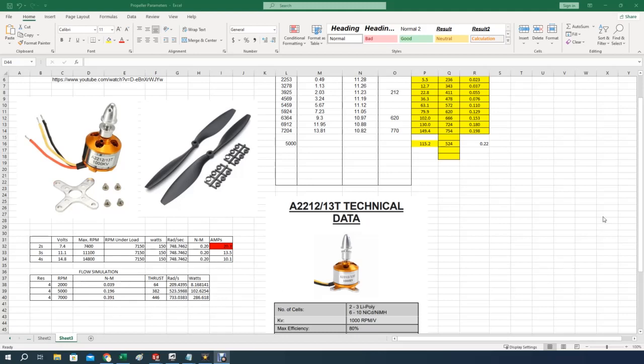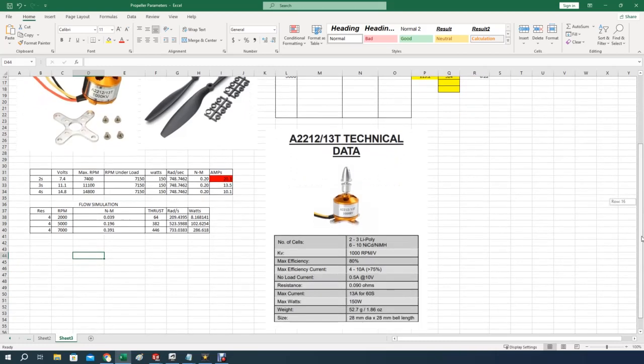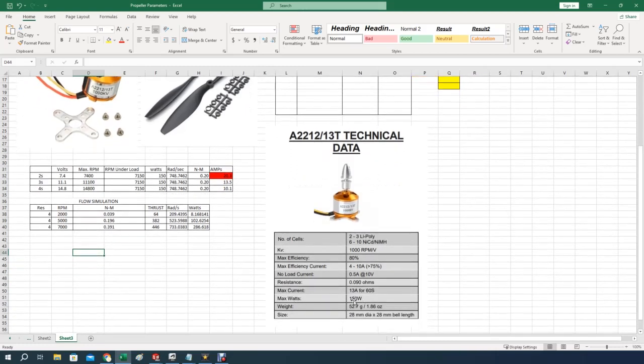So eventually, the conclusion from that study was that watt is more important. Well, both are important because watt depends on torque as well as RPM. But eventually, watt will pick both of them, RPM and torque, just to see where we are. The idea is that I need to calculate what the RPM is for 150 watts, because that's actually from the spec, which clearly says that we cannot go above 150 watts.